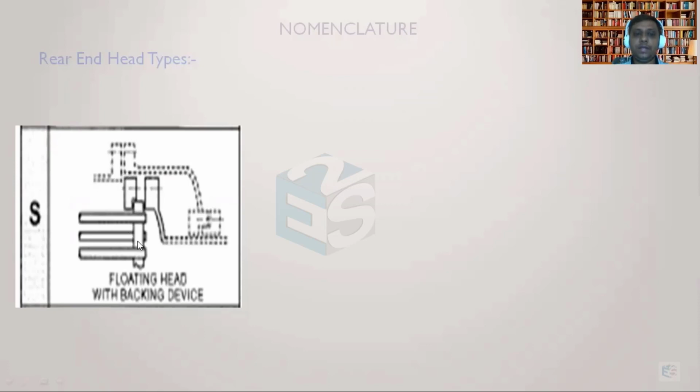It will have a tube sheet which is called a floating tube sheet. It will have its own head, which is called a floating head. This portion, the floating head along with the flange, will be there. Then there will be a split ring placed on the other side of this tube sheet, against which the nut and stud assembly will be tightened. So this tube sheet will have a gasket in between the head and the tube sheet. That gasket will get compressed.